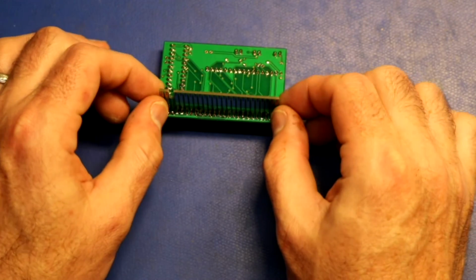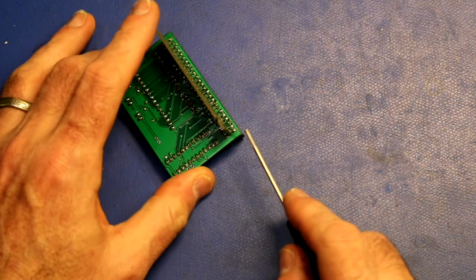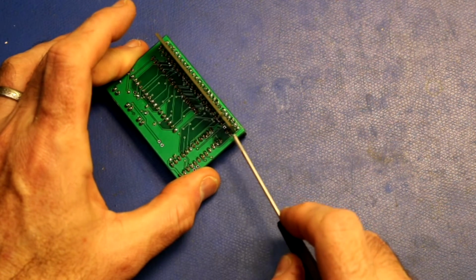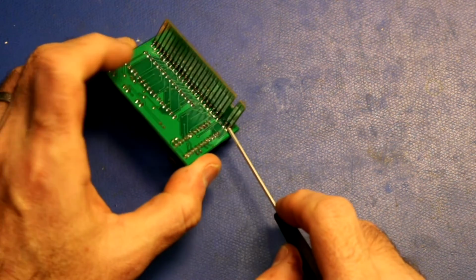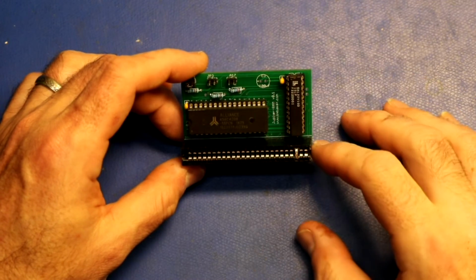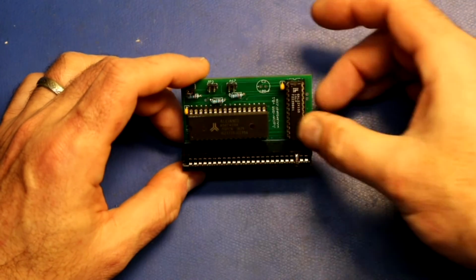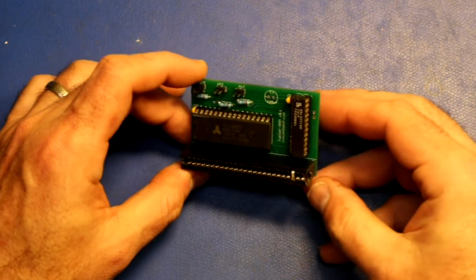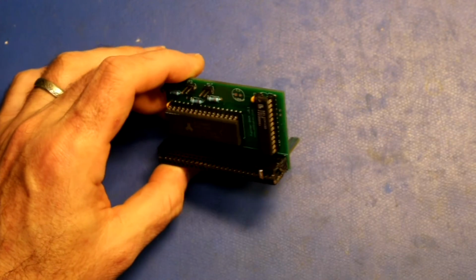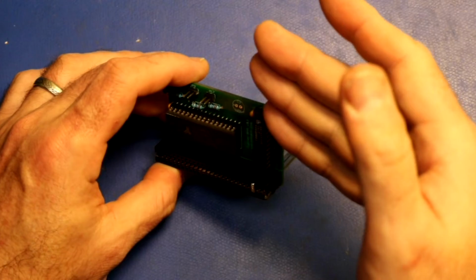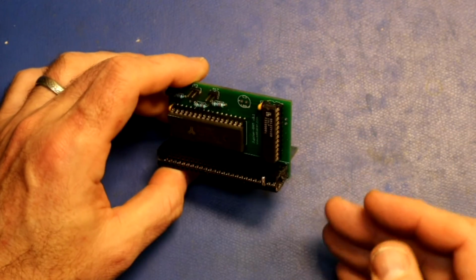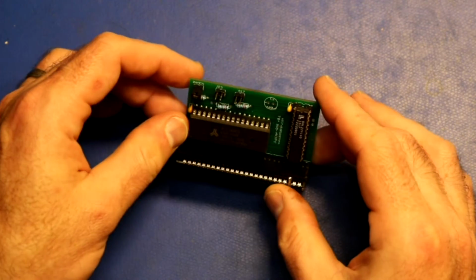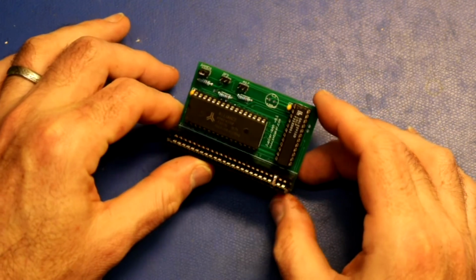Then on the back side, I made this little coupler connector, and you squeeze the pins that came from the card edge connector together, and you can solder them to the main PC board as well as to this coupler PC board. Now I realized after making these that I should have flipped and put all the components on the back side rather than the front side. If you look at a ZX81 16K RAM module, you'll notice that it's in a plastic case, and the front of the case comes down kind of flat against the PC board. So I'm not sure I could really put these in a case unless I flip all those components to the back side. So I may respin these boards to do that.